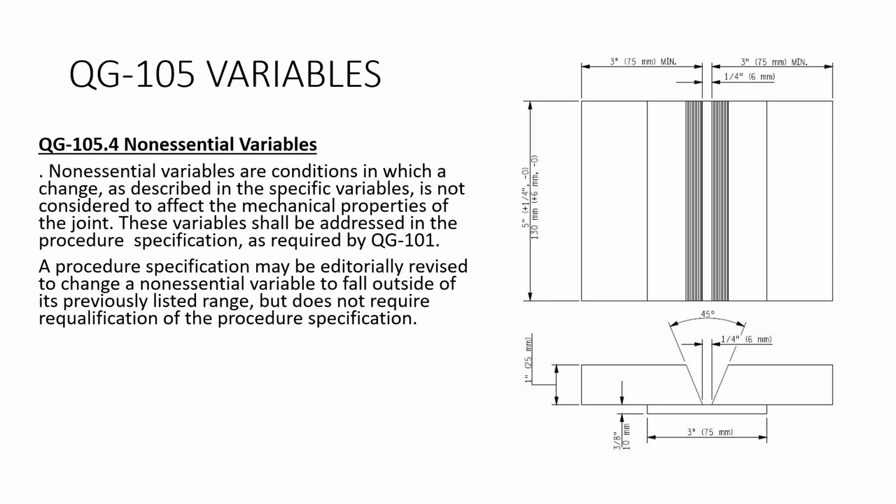You need to wire brush it 7 times, and whatever. So that's why we have it listed here, because it needs to be addressed and you need to provide guidance. But if we change it editorially, we revise it on the WPS and put out another revision and move on. We don't have to do another qualification test.